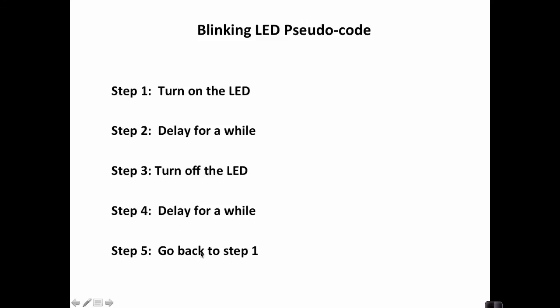So the branch instruction works exactly the same way, except instead of branching always, the condition code will use a branch not equal. So for example, in your loop, you can have some register that's your counter register, and each time through the loop you'll add a value to that counter register, and then when you go to branch, you can branch if it's not equal to 1,000,000 or whatever constant you decide to use.